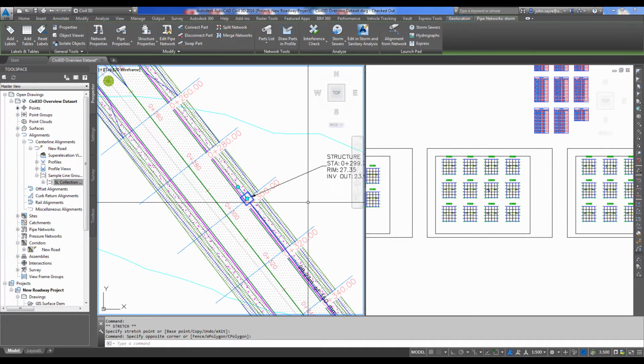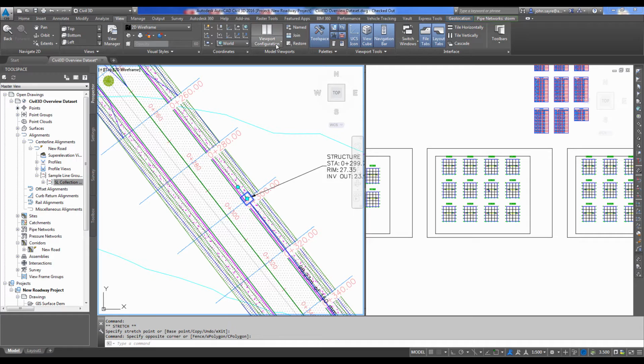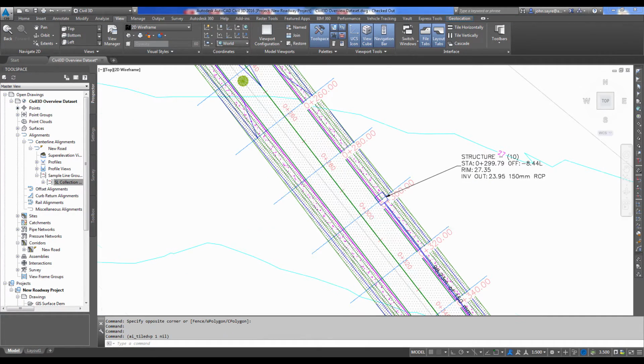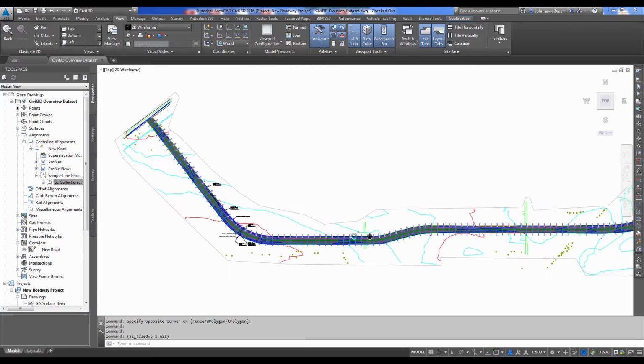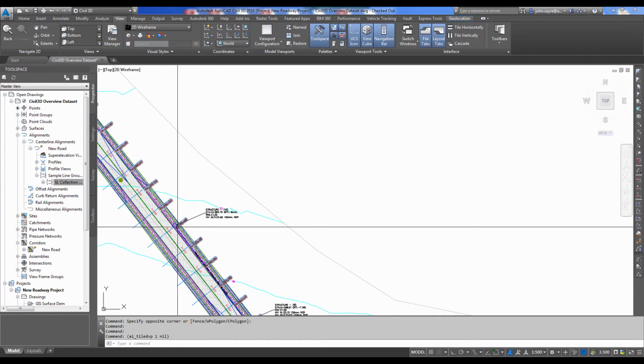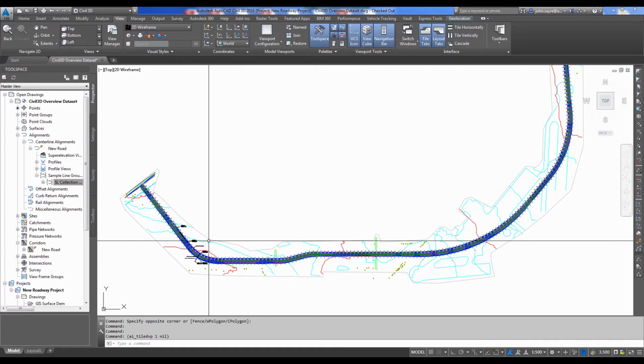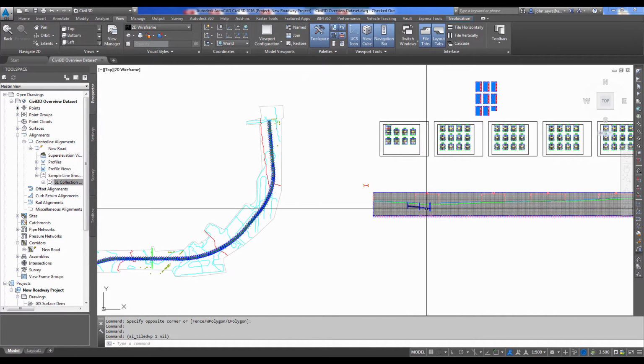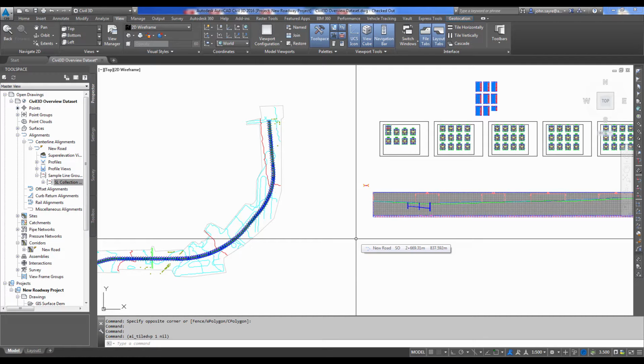So literally, I guarantee this is a scenario that you've had happen. You get all your utilities and everything designed and pushed to the right location, and something happens and one of them needs to move. Think about all the places that is touching, meaning that inlet right there. It's going to be shown in cross sections. It's going to have its own alignment and profile most likely, or at least in some companies it would. It's going to be updated in the profile view. If these were already in design sheet form, we would have to go in and actually hand check where those pieces and pipes have moved to make sure that it reflected the actual design, the new design.